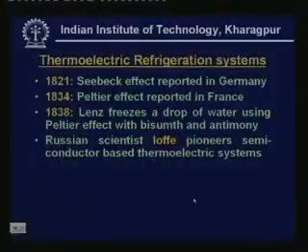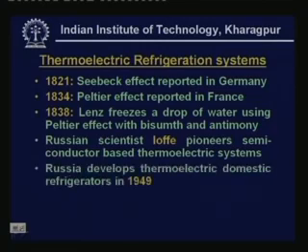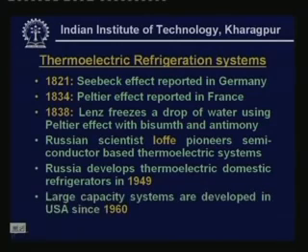And later, the Russian scientist Ioffe was one of the major pioneers in the area of semiconductor based thermoelectric systems, and Russia has developed several domestic refrigerators using this principle. And in the USA in the 1960s, they developed large air conditioning systems using the thermoelectric principle. One major problem with the thermoelectric principle is that the efficiencies are typically low compared to vapor compression systems.